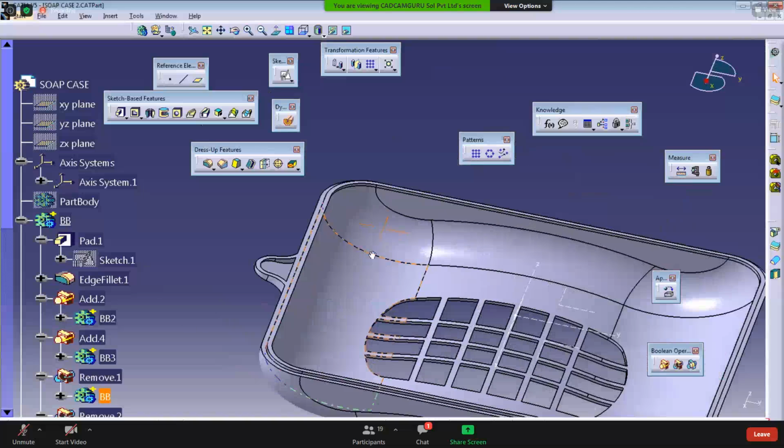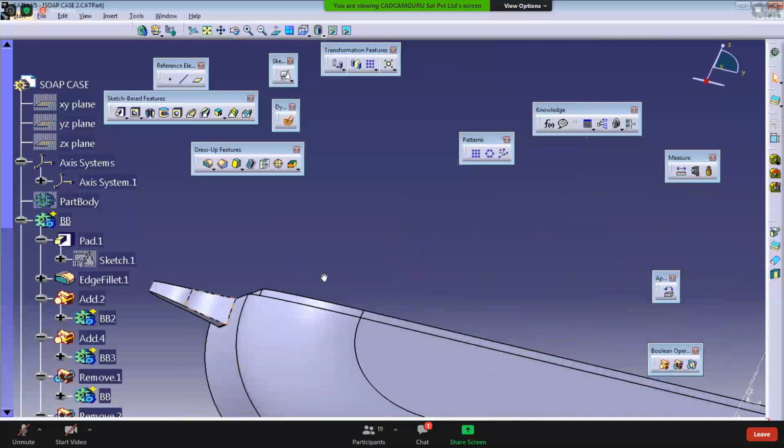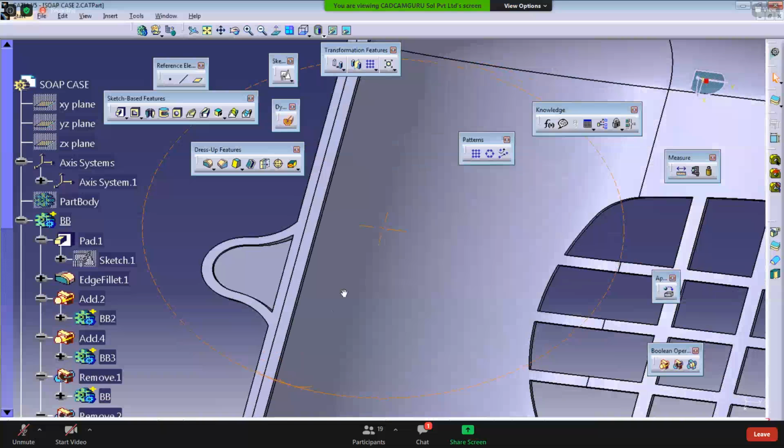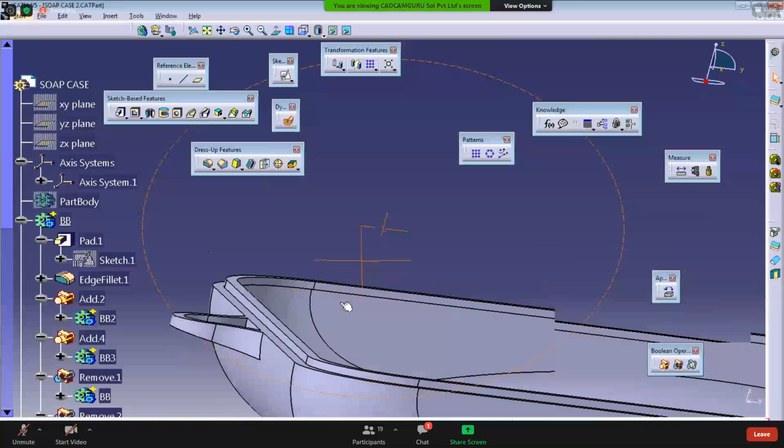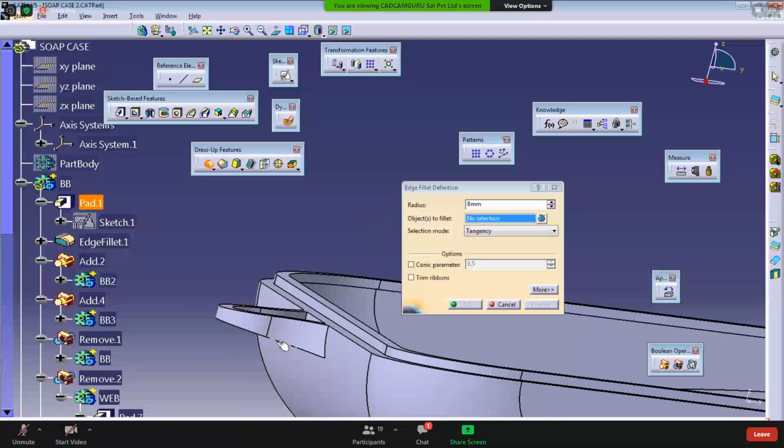So that is the benefit of intersect. From the front view it looks like a different shape, and from the top it looks like a different shape. Such results are there. Then the resultant body we can generate through the intersect option. Clear? And whatever the pending work, that is the fillets, you can define later.